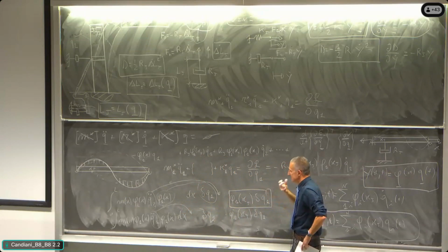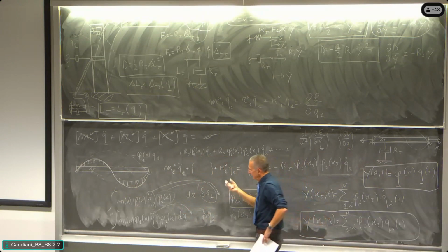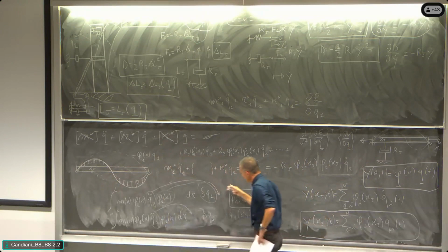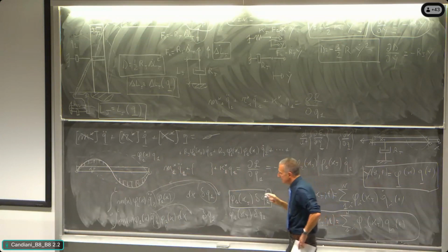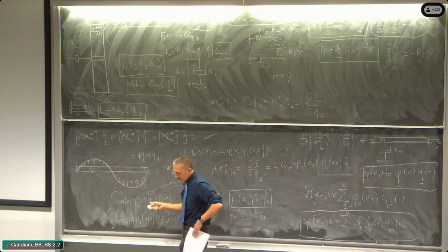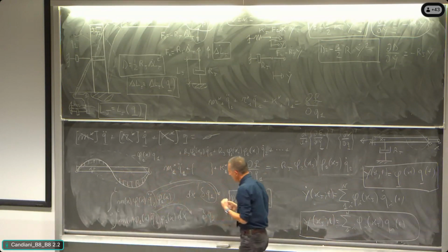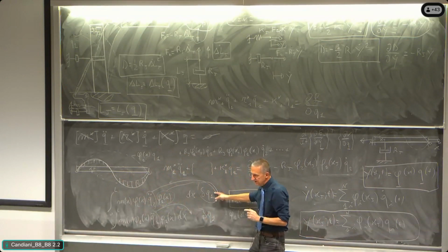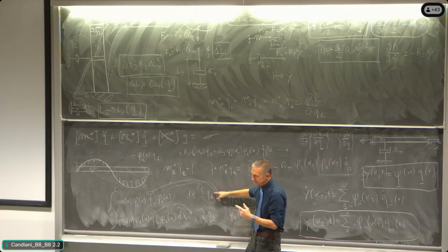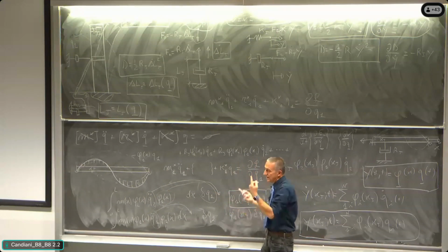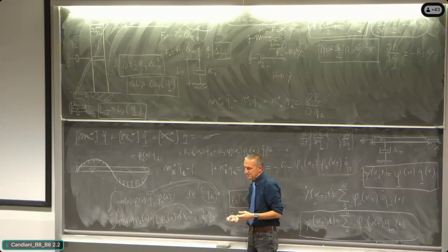So I tried to help you to understand that we are writing the effect of those distributed forces through the principle of virtual work, and all of that is making the distributed action be weighted by the distributed displacement associated to the coordinate with respect to which we are writing the equation, all right? And so, of course, if it is 1, 1, we have the first modal mass.